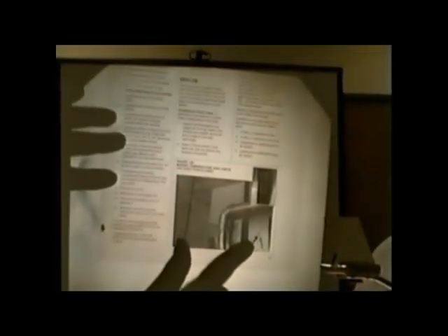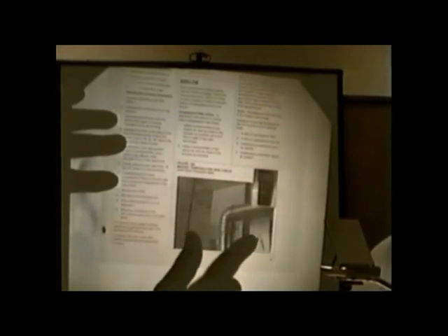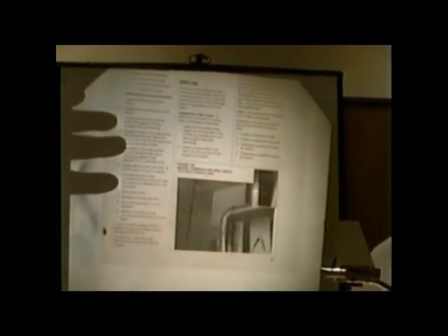The point is, it's talking about checking airflow and taking temperature rise, and they're using an electronic thermometer to do this. We put a thermometer in the return. Are you able to see that there? I don't know if you can get a close-up, but that's okay. We're putting a thermometer into the return, and we're also putting one in the supply. Let me do this, Jeff.